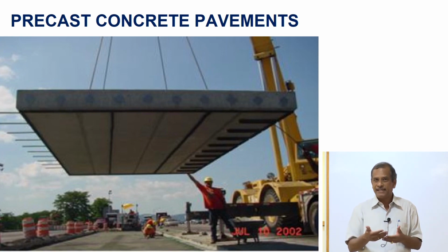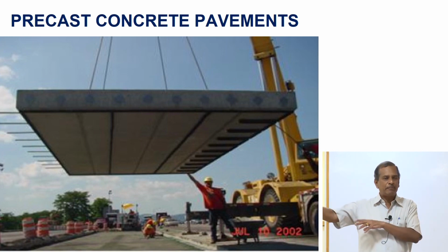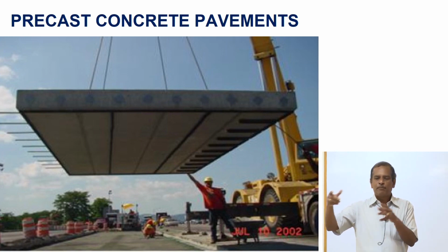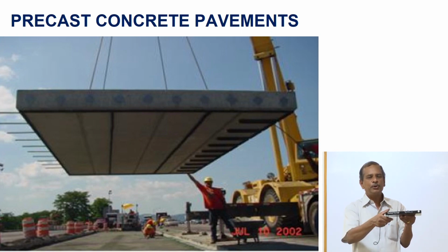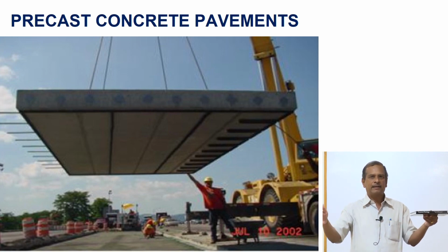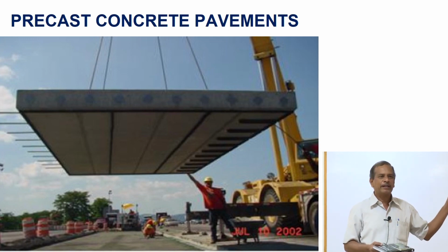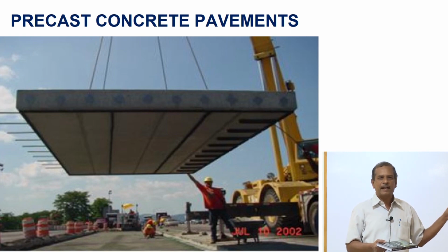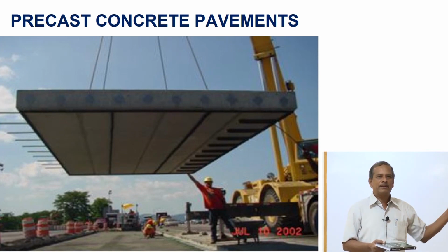Alternatively, it's time that we look at precast concrete pavements. Can I fabricate these concrete pavements elsewhere and bring them to a site? I can fabricate slabs like this, bring them to a site, assemble them, and then open the road to traffic. You can do a post tensioning after you fabricate all these and arrange them in the section. We have started adopting this for the first time in the country for the outer ring road at Nagpur. A research work is in progress at IIT Nagpur today. So concrete pavements, I think it's time that some of you can become an entrepreneur, can have a company for precast concrete pavement.